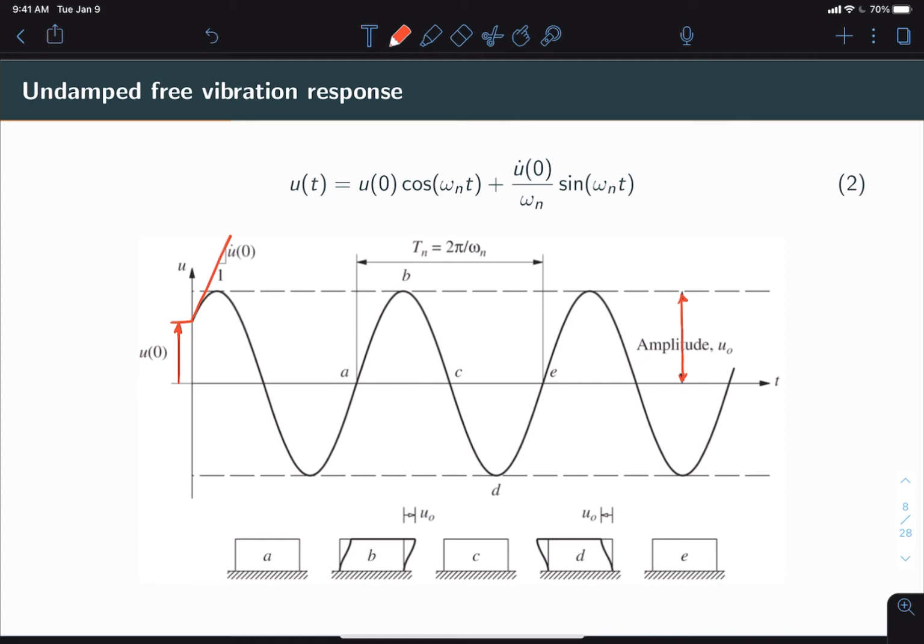So what is happening? Whenever this curve crosses 0, as in this case C, our single degree of freedom system, which we're using a frame for in this case, is simply at the equilibrium position. We're plotting displacement after all, so displacement is 0. When it peaks, it means that the system is at the maximum point of displacement. In other words, it's pushed all the way out to one side.